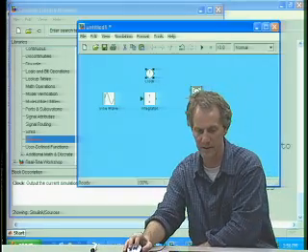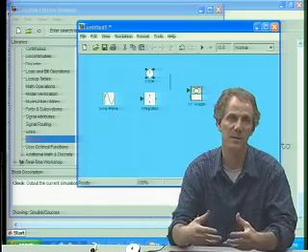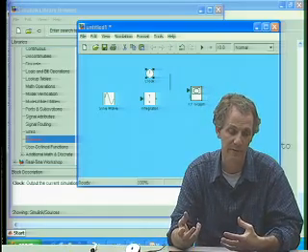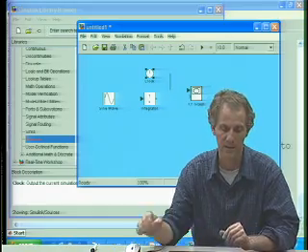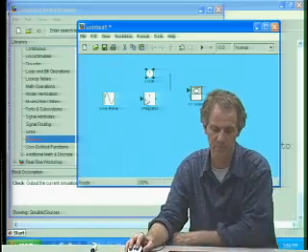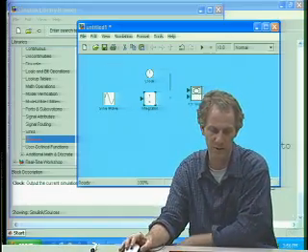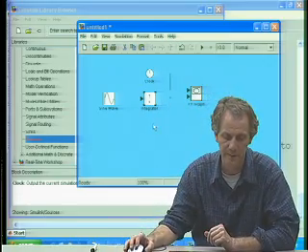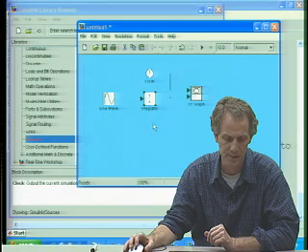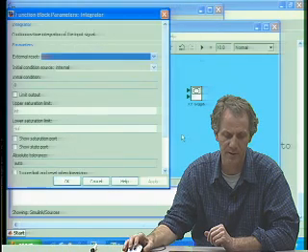Clock, there really is no x. Simulink is all about integration with respect to time. So clock is going to be the x value, the horizontal axis, and then the y value will be input from the sine function, or actually the integration of sine for this plot. And I do have the option for an initial condition.